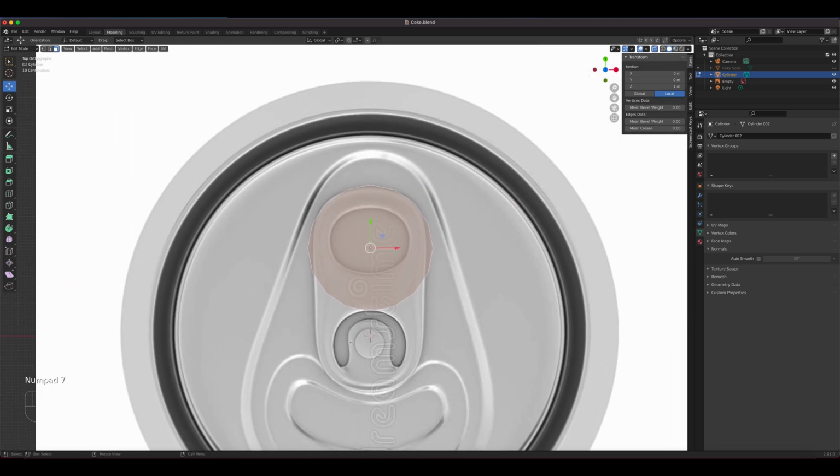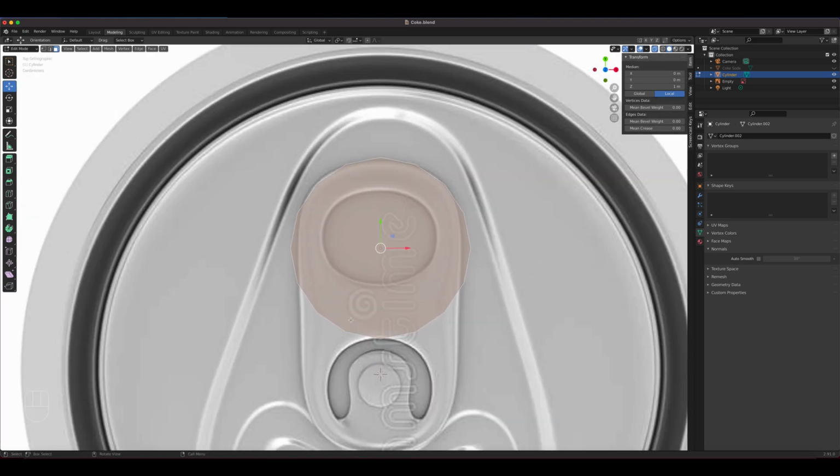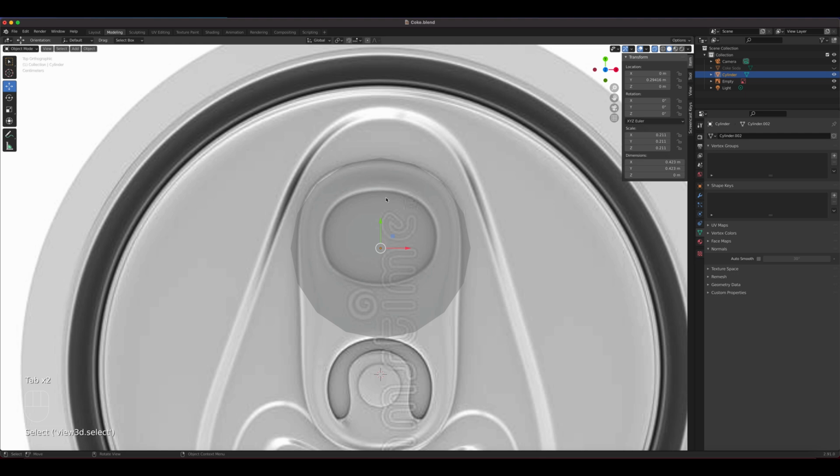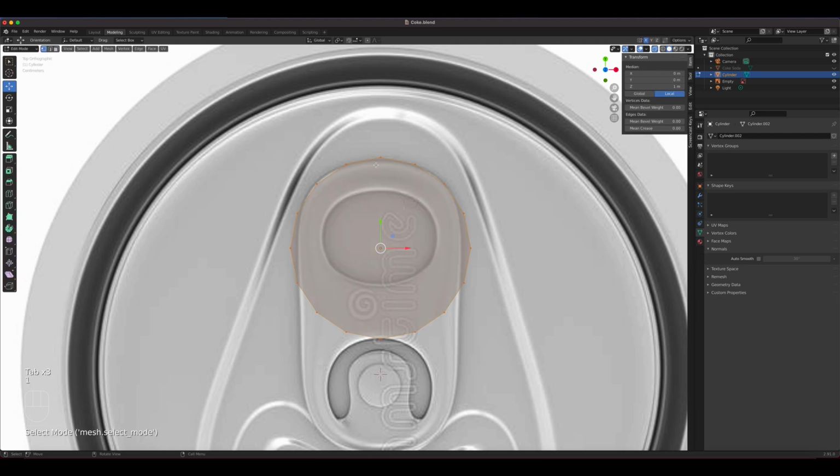All right, and you probably know the drill at this point. We're just going to press I and then do all that stuff, right? So I will symmetrize this. Press X right there, and then hit tab, edit mode, point mode. Symmetry is on, so I'm going to again follow along on that one. We might need to move some of this up. It's probably going to go here.